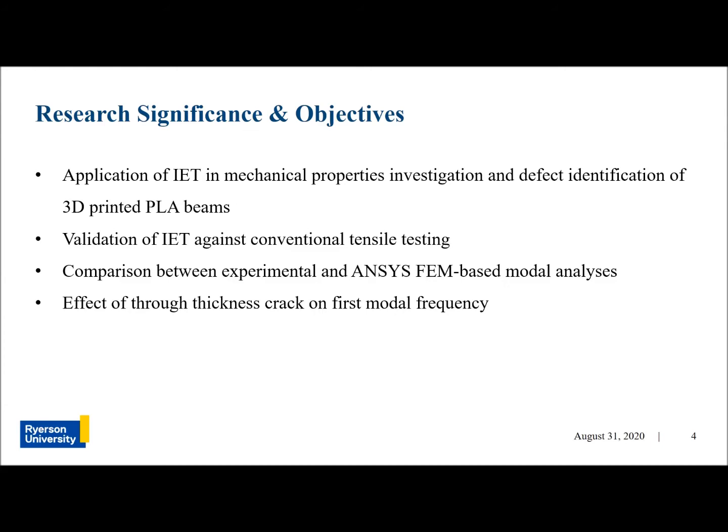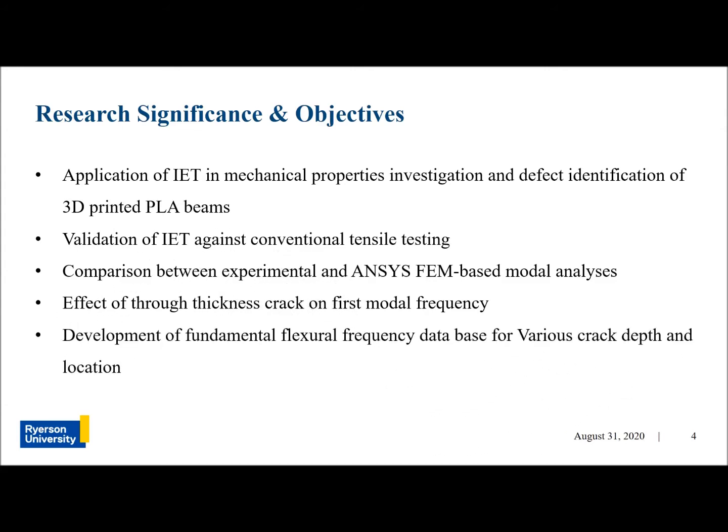Using the same methodology and by employing IET, the flexural strength of intentionally cracked beam samples will be studied at different crack sizes and locations. Using simulation ANSYS-based modal tests on 81 intentionally embedded crack beam samples in a wider range of locations and sizes, a crack depth and size versus fundamental frequency database will be presented.